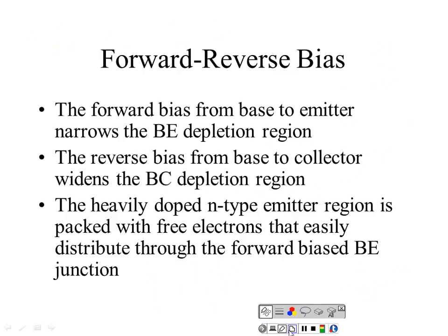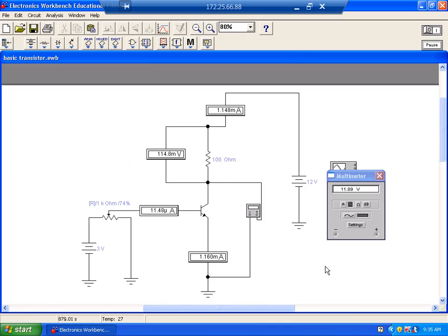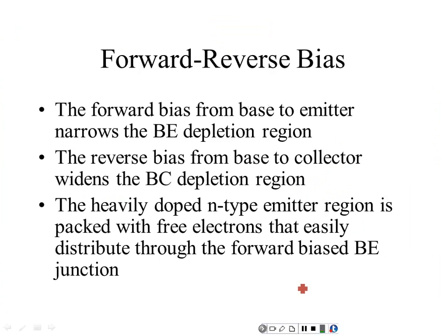So this guy here has a gain of 100. Now that I know the gain, I can say, okay, what would be the current flow if I change the base current? So if the gain, which we call the beta, is equal to IC over IB, then what's IC going to equal?